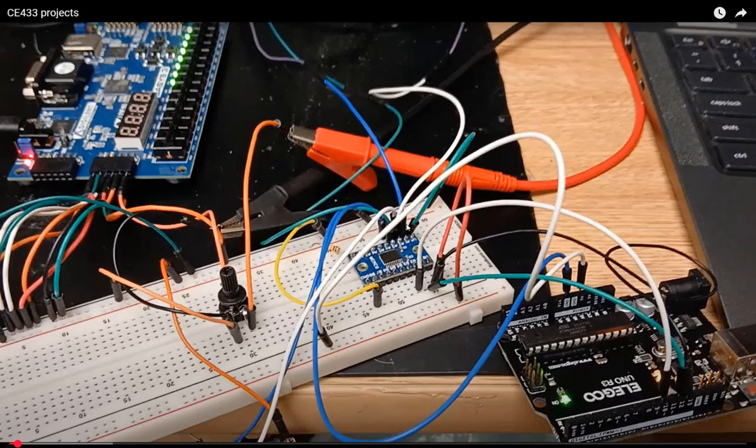So I talk about this a little bit in the video, and what's happening is there are 2 columns of pins, and on one side are 8 A pins, called A1, A2 until A8. And this is VA. So connect VA to 3.3 volts. And there's the OE. It's the enable pin. The enable pin should be put up to 3.3 volts. So I'm using a 10K resistor and just connect this pin to 3.3 volts through a 10K resistor.